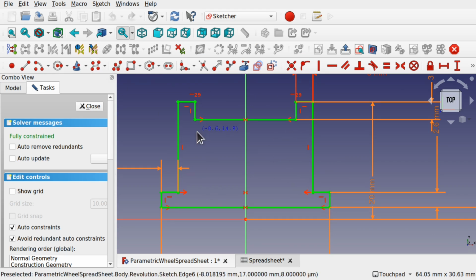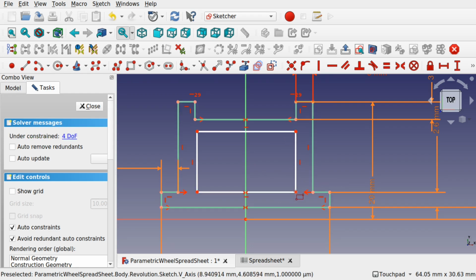So I'm using the rectangle tool and create a rectangle in here. This will become a void then. So I can take these 2 points and keep them in line, the same as these 2 points. And I'm going to do the same here. And really what I should have done is selected the horizontal constraint and click one, click the other. Those are in line now.